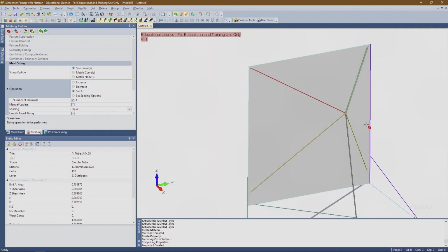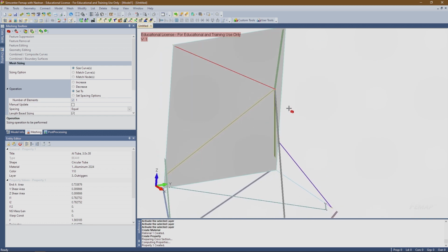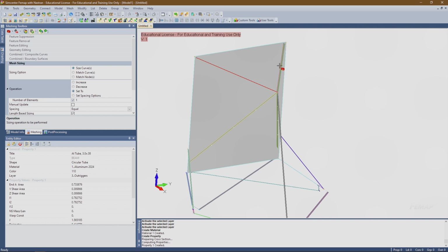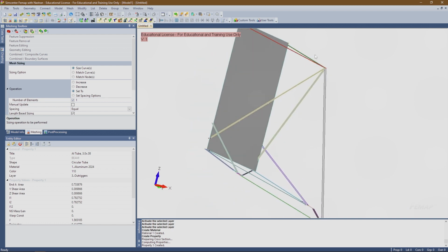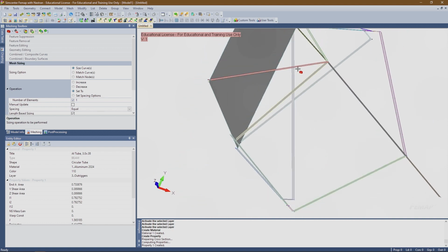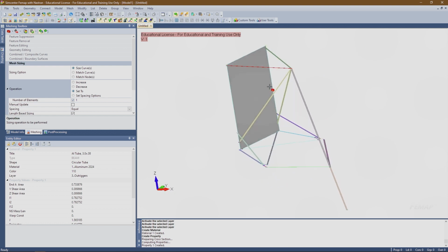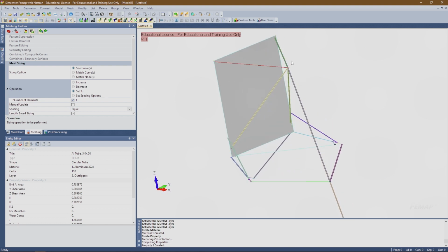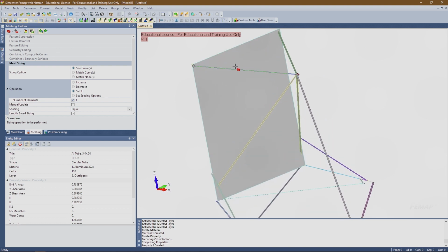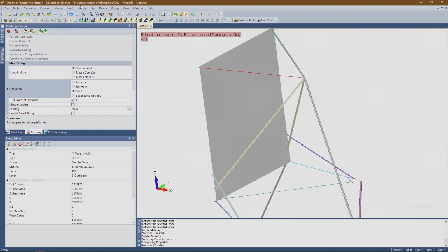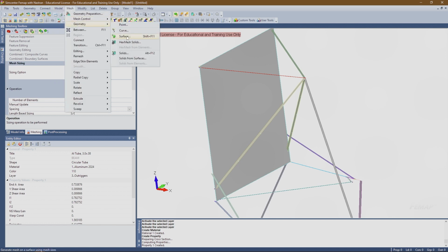You can certainly do a taper with multiple elements, and it's quite easy actually. It just takes more time, and you need a bunch more properties to make sure you represent the full taper. So just for ease of my life doing this video, I'm only going to do one element for the taper, but you can certainly do 4. Okay, so now we're going to go to mesh, geometry, and curve.